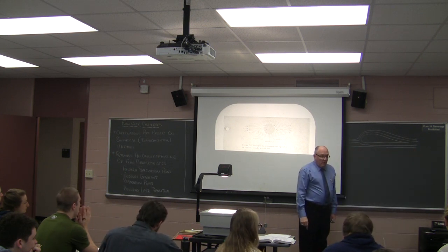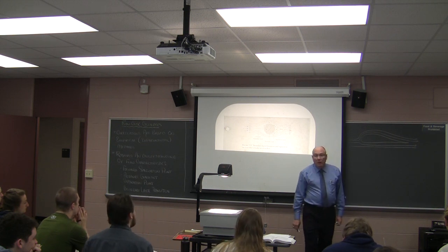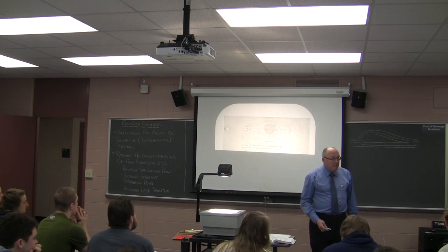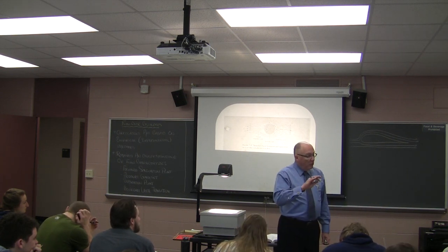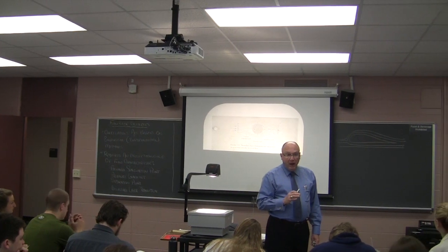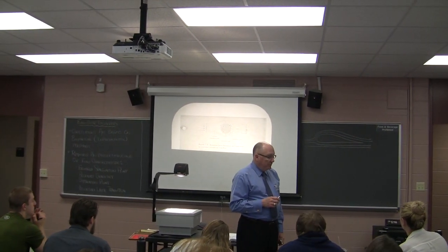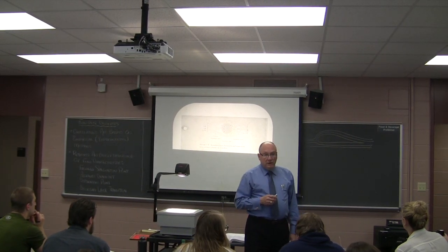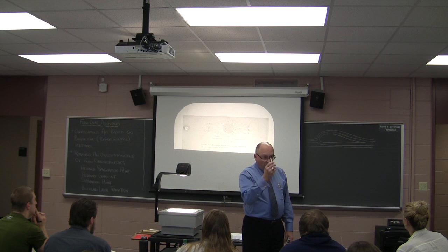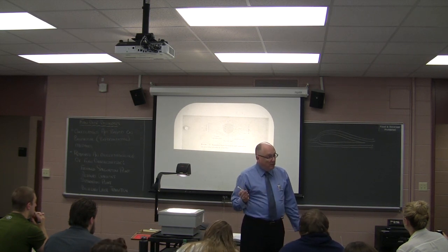So, the flow on the bottom of the aircraft wing, this is an asymmetric aircraft wing. Airfoil is the appropriate name. So, for an asymmetric airfoil, the flow has further to go over the top of the wing. It goes faster. What happens to its pressure? It decreases. Bernoulli's equation. So, what do you get? Forces acting underneath the wing, pushing it up, and that is called lift.